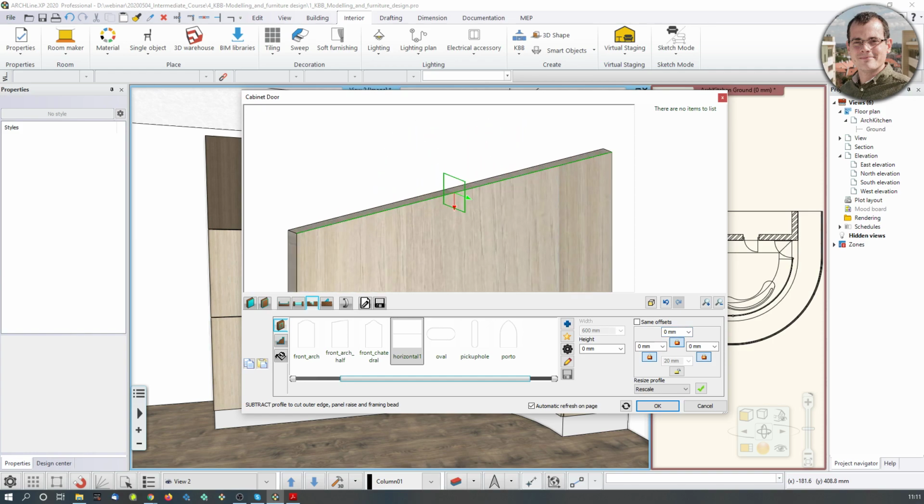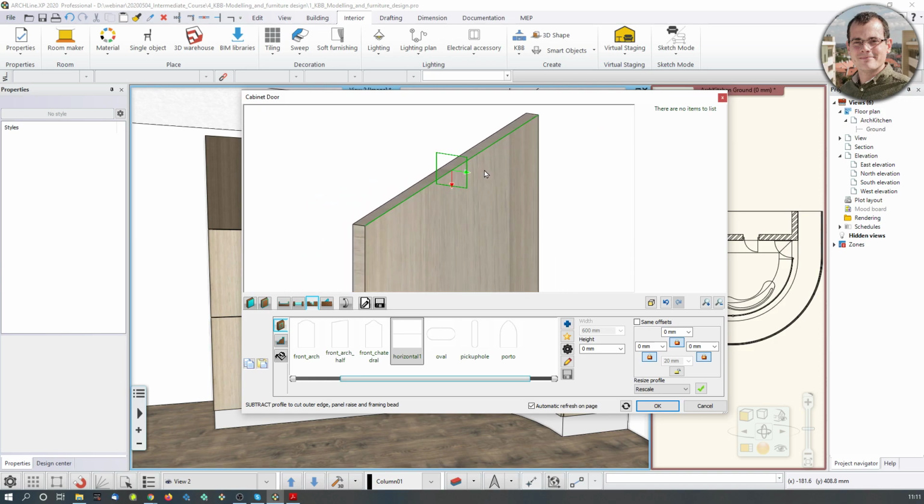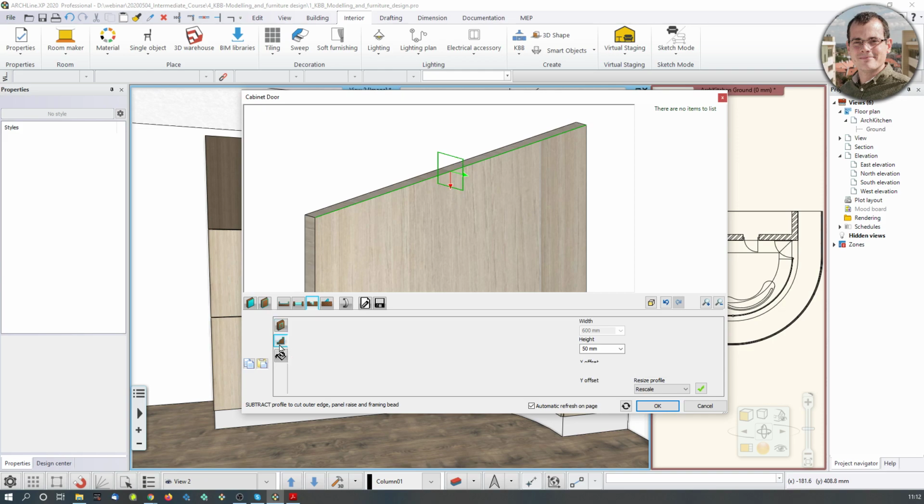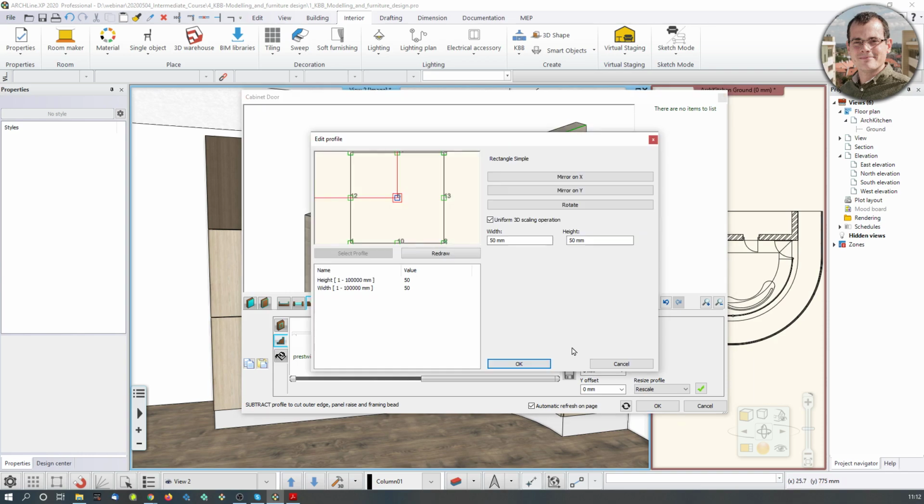Are we done? Well, not really, because the next thing I have to do is fine-tune how my, let's call it a blade or a milling machine, whichever you prefer, so how that section profile looks like. And that I can define here with the profile. I think the rectangle is fine for me. But one thing is not fine, and that is the size, which I can change here. So the size should be, I think, 40 millimeters times... scaling, uniform scaling has to be disabled, otherwise the software is going to readjust the two sizes. So this has to be 20. I think this is done.